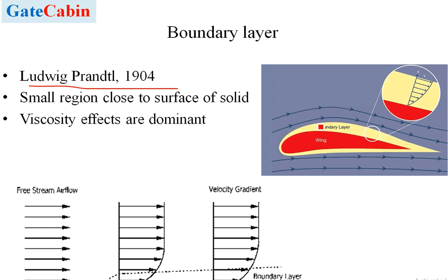So this region is basically a viscous region where viscosity plays an important role. Everywhere outside this region, the viscosity effects are not so prominent and all the fluid is moving with the same speed, so we can say that the fluid is relatively at rest. There is no shear happening here. So this region is known as the potential flow region, an ideal region.